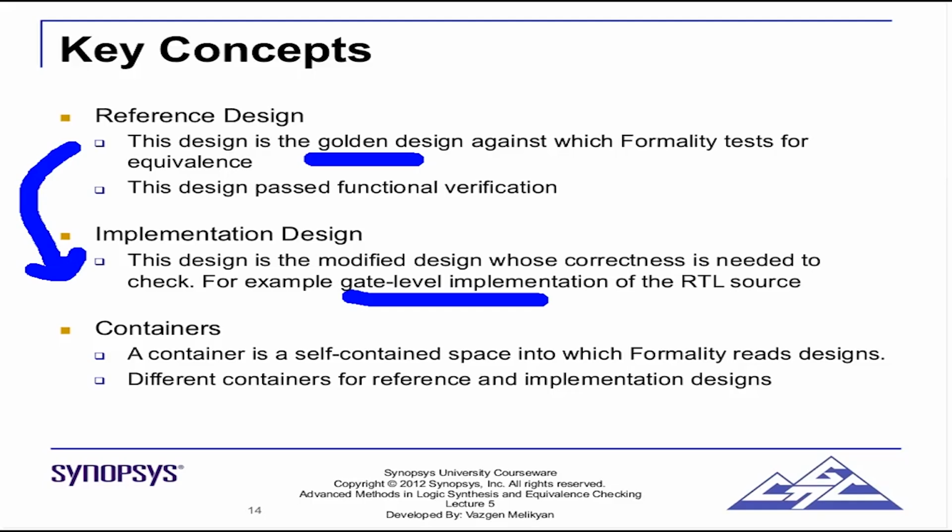Then there is a term called containers used by Formality. A container is a self-contained space into which Formality reads the design. Formality reads two designs: reference design and implementation design. For the reference design, Formality will form a reference container. For the implementation design, it will form an implementation container. So you have different containers for reference and implementation.